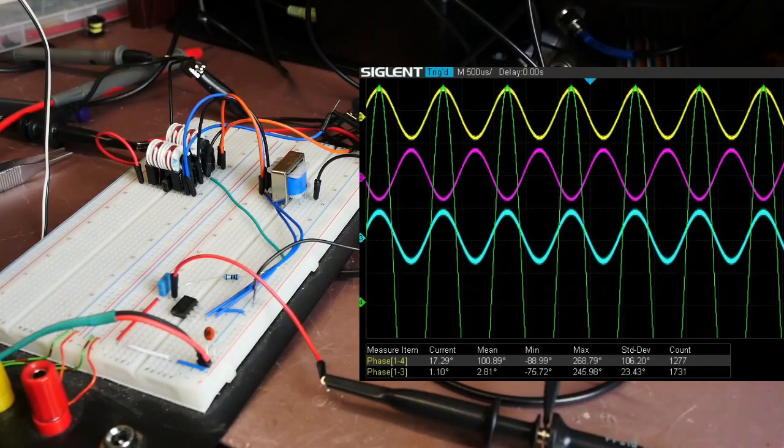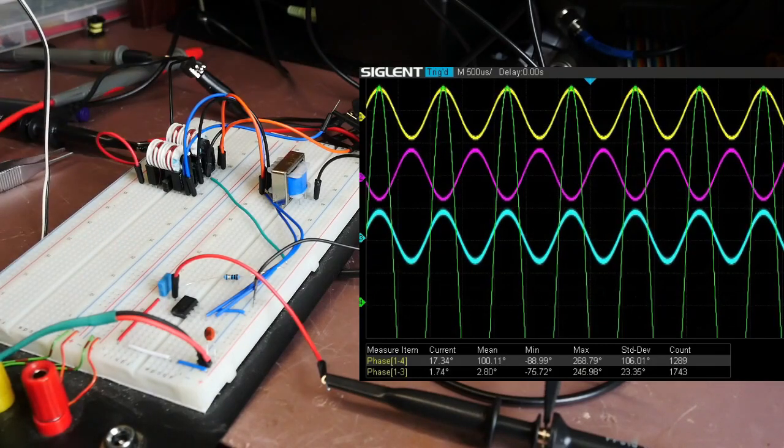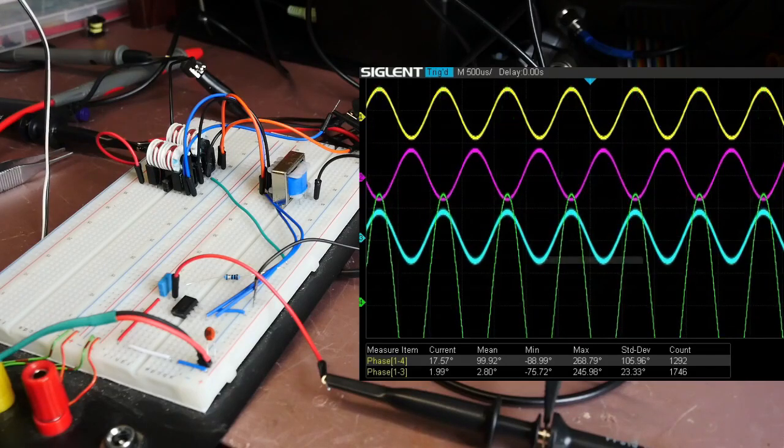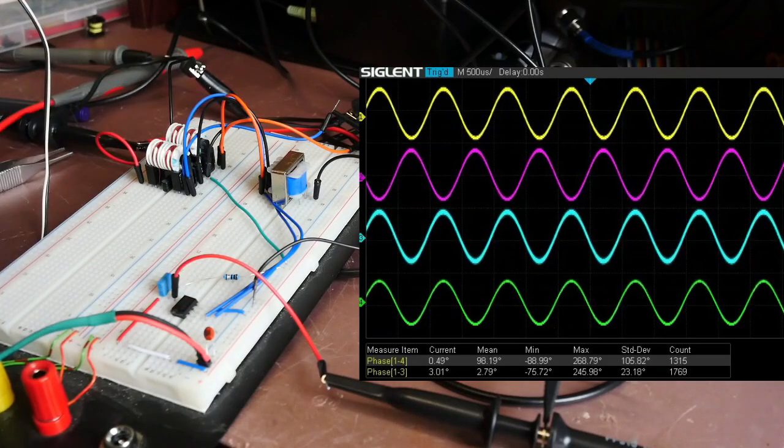And the first thing to notice is we've got a very large off-scale green trace. Well, not surprisingly, the op amp is amplifying, and because it's quite a powerful audio amp, we're going to need to back off the volts per division there. And if we now change that, you can see quite a lot of amplification, but if you look at the phase difference between the yellow and the green trace, as per the measurement, it is in fact in phase. So two out of phase signals being fed into the plus and minus inputs of the differential amp, and we've got an in phase signal coming out, in sync with the signal that went in.